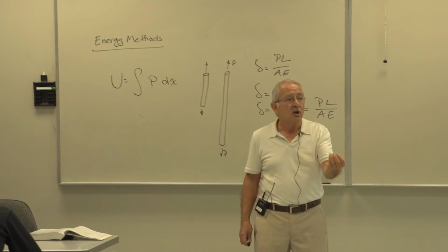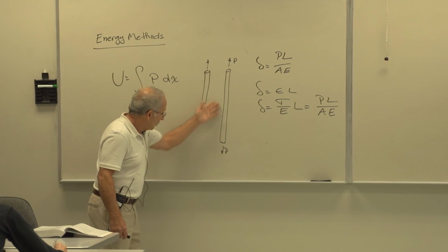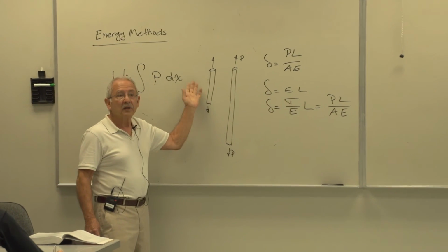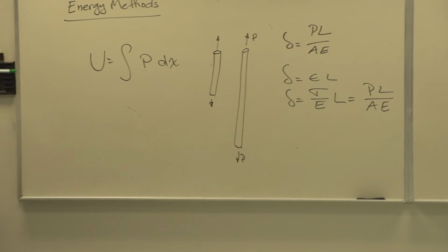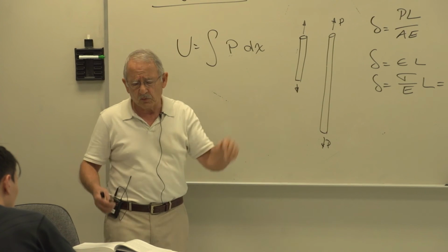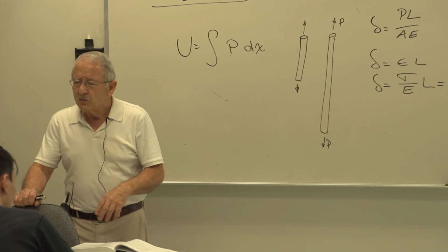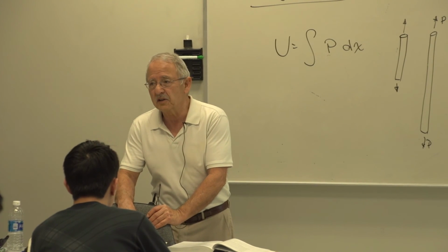So energy is a function of not just the applied load and the material, but also of dimensions. And the same is true if you change the area, of course. So in order for us to be able to compare those two, if these, for example, were made of two different materials, we have to take out the effect of volume, dimensions, that is.